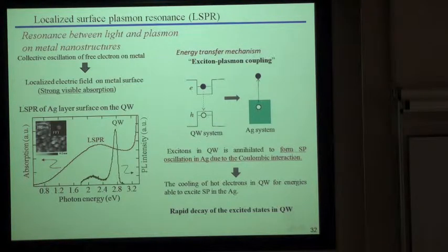And finally, I show you the local surface plasmon characteristics of one of these typical materials. For example, the luminescence shows the quantum well peaks observed around the cadmium zinc oxide bandgap, and when we form the silver dotted patterns on that, the plasmon absorbance is located around the same region.